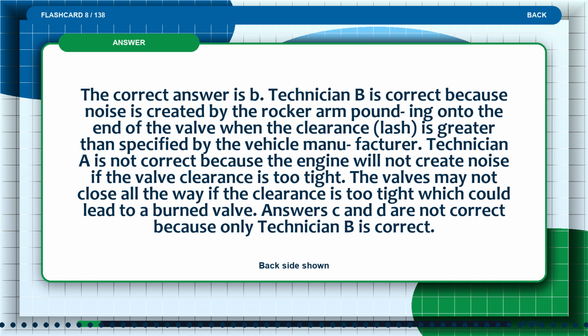Technician A is not correct because the engine will not create noise if the valve clearance is too tight. The valves may not close all the way if the clearance is too tight, which could lead to a burned valve. Answers C and D are not correct because only Technician B is correct.